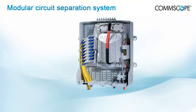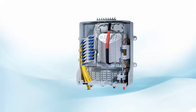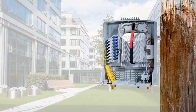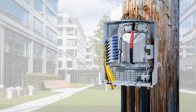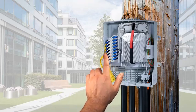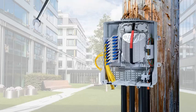The easiest way to increase fiber capacity is to add as many fibers and cables as possible in the equipment. This results in splice trays with more than 96 splices per tray. The drawback of such mass storage systems is that during an intervention by a maintenance crew, many fibers or cables will be touched, either intentionally or by accident. The probability of an uncontrolled fiber bend becomes high, resulting in rapid changes in attenuation, also called transient losses.